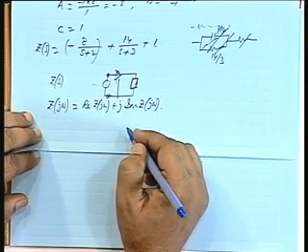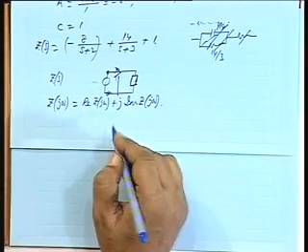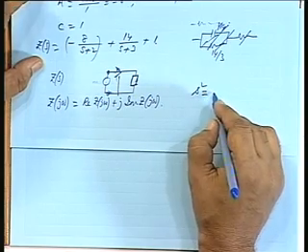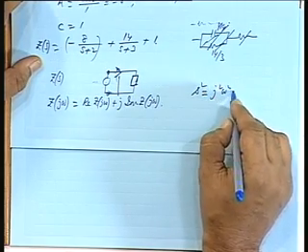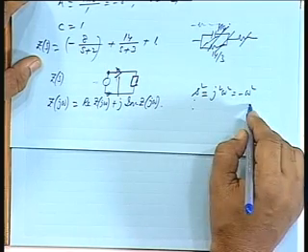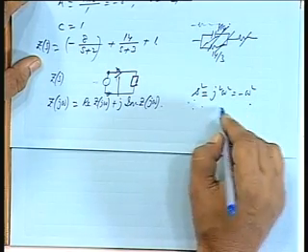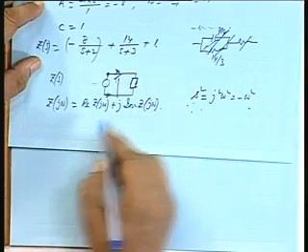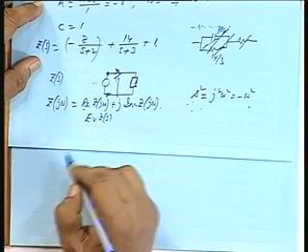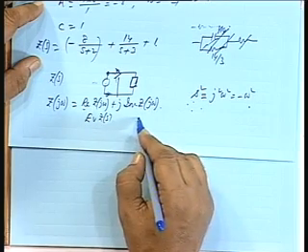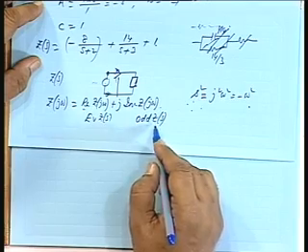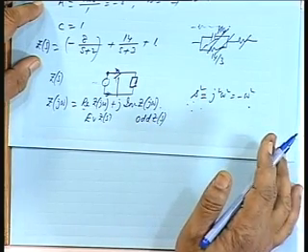Now, if I put S equal to j omega, if there are S squared terms, it will be j squared omega squared, that will be minus omega squared, it will be real. So, all the S squared, S4 terms will be real, and S cube terms will be imaginary. So, real part will correspond to the even part of ZS, and the odd part will be, if I put S equal to j omega, in the odd part I will straight away get the imaginary part. Is that all right?